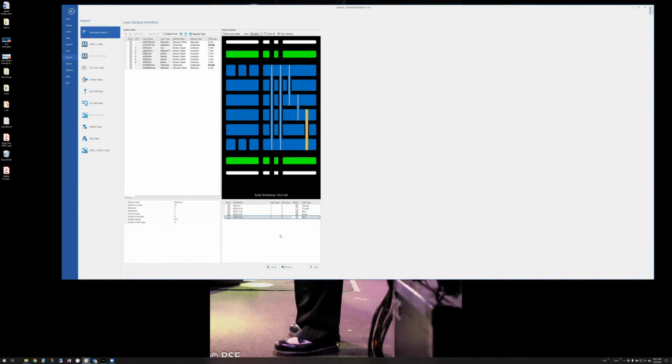Now, I'm doing it at the layer level here. That's not always possible. As you know, a lot of times you get drill files with all the drills in one drill file, plated or non-plated. But you can do that out at the drill and mills table to change the plating characteristics. But by doing it here, it just gives us a little head start.